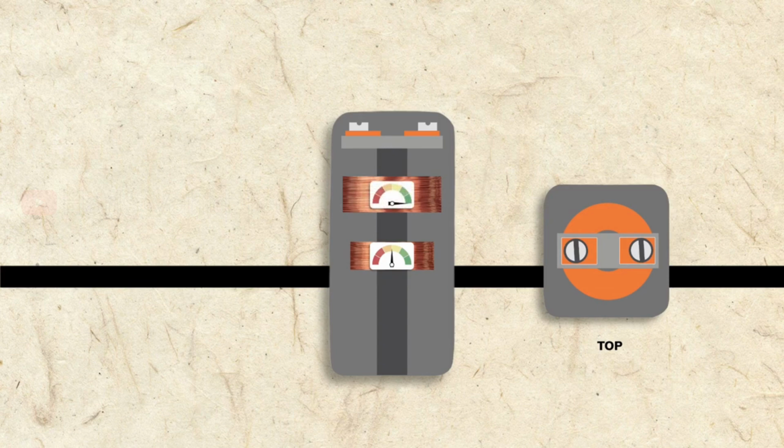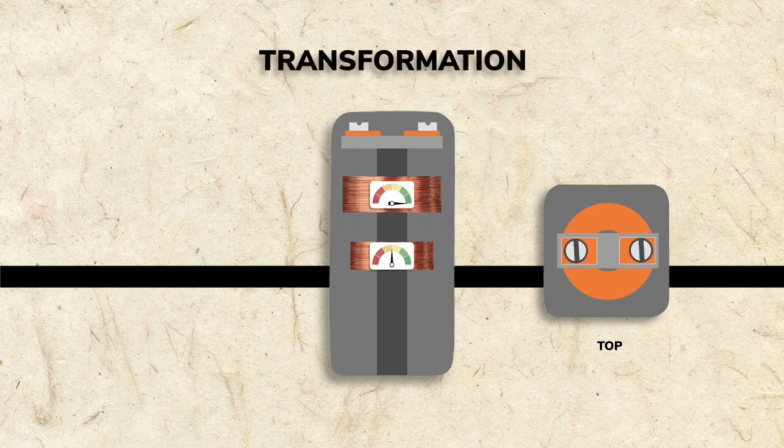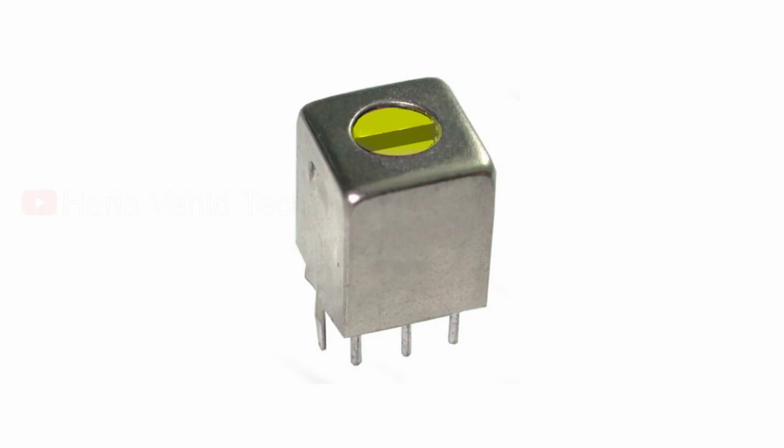Why are intermediate frequency transformers used? Intermediate frequency transformers are used for three general reasons. Number one is, at very high frequencies, signal processing circuitry performs poorly. Active devices such as transistors cannot deliver much amplification. Ordinary circuits using capacitors and inductors must be replaced with complicated high frequency techniques such as strip lines and waveguides. So a high frequency signal is converted to a lower intermediate frequency for more convenient processing.